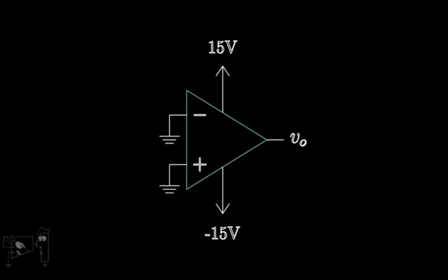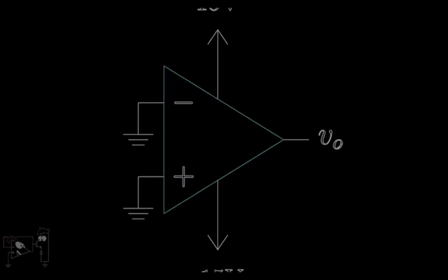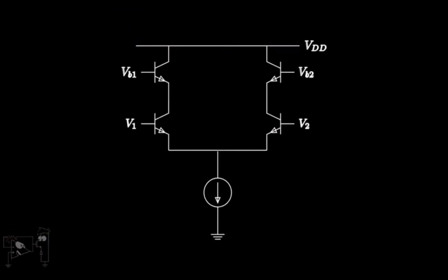To understand why we get this offset voltage, we need to take a look at the internal structure of the op-amp. The first stage of an op-amp consists of a differential amplifier. Differential amplifiers ideally need to be symmetric. However, during fabrication and packaging, several mismatches occur. Hence, even if we apply the same input to both the terminals, that is 0 differential input, the bipolar transistors sensing the two inputs may display slightly different base-emitter voltages, what we call biasing voltages. The same effect occurs for MOSFETs. Thus, the op-amp sees a differential input and amplifies this, to give us some offset output.